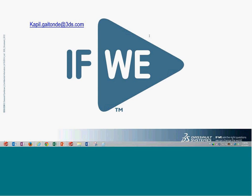Then there is a question on how efficient it is. Put it this way, it is directly proportional. Because it is parametric, because it is within SolidWorks CAD, it is directly linked. So definitely efficiency in terms of handling it is very good. You have direct control on the parametric model. The effect on efficiency could be in terms of solution time. Obviously, the more the parameters, the more the solution time, and there is no shortcut for that. It depends on the hardware capability, and it should be quite fast.